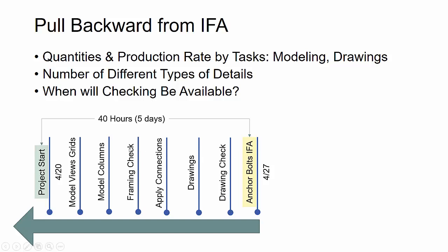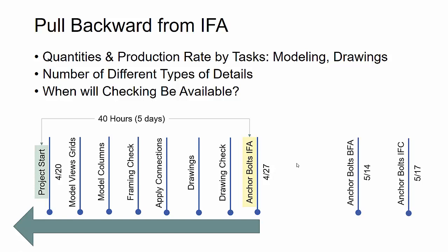And if you just physically can't make it even after tweaking things, then you go back and talk with the fabricator way back here at the early project start, versus way up here a day before you actually do your submittal. Now, once you do go out for approval, this is the next part of steel detailing management and lead detailing schedule management. If the job has multiple submittals, like in this case, I had one total structural submittal and then one submittal for anchor bolts and embeds.